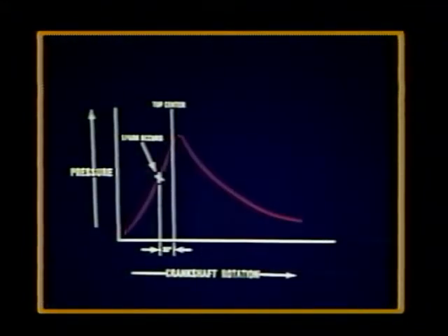When the mixture is ignited at this point, the pressure will continue to rise until it reaches its maximum when the piston passes top center. At this moment, the maximum amount of push will be exerted, and it is at this point the power will be the greatest.